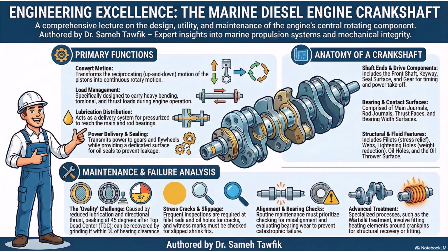But why 6.25 inches specifically? I mean, when you see a tolerance or a design restriction that tight in a source document, it really makes you pause. If an engineer is designing an oil thrower surface, what happens if that engine's bore is, say, 6 inches or 6.5? It comes down to the precise velocity and volume of the oil being sheared and thrown by the rotational mass. It's interacting with the specific geometry of the crankcase. The sweep of the connecting rod, the distance the oil has to travel to lubricate the cylinder walls or cool the underside of the piston, all of that is calculated based on the bore size. So it's perfectly calibrated. Exactly.